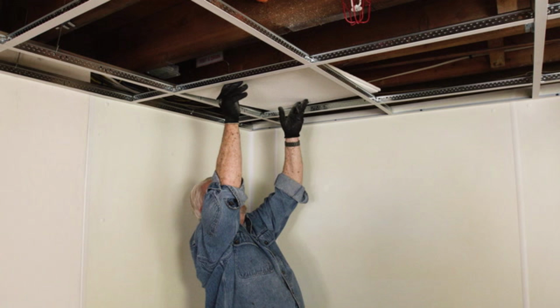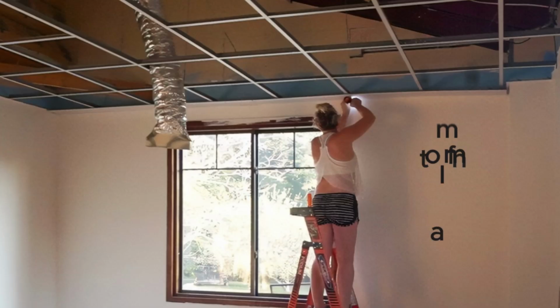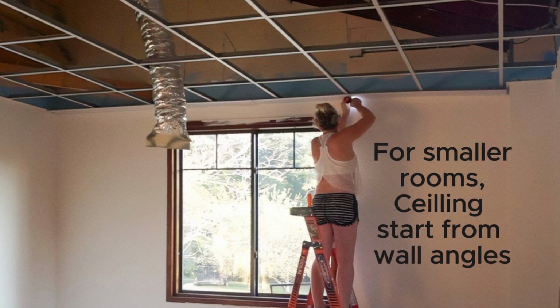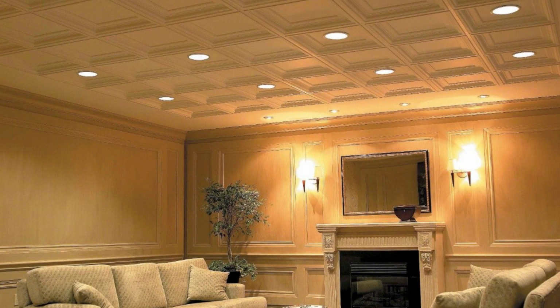For smaller rooms, bedrooms, bathrooms, kitchens, work from the wall across the room. Set the perimeter using wall angles. Measure and install main tees directly from the longest wall. Fill in cross tees every 2 feet. Cut tiles to fit against the walls where necessary. Install lights and vent tiles.